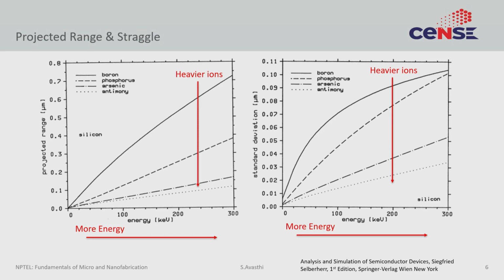The other things that you can control in the ion implantation is the acceleration voltage, how fast the ion is going by the time it impacts on silicon, and that can easily be controlled by just controlling the various voltages in the ion implantation system. That is what is called the energy of the implant. Okay? So, these are the two parameters that the ion implantation machine controls. It controls the dosage, which is the total number of ions, and it controls the energy.